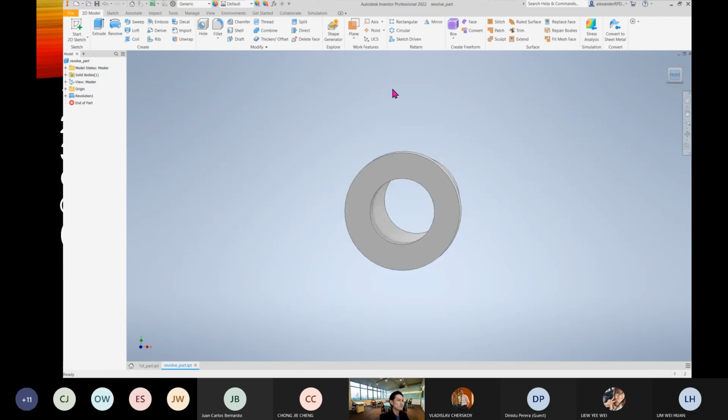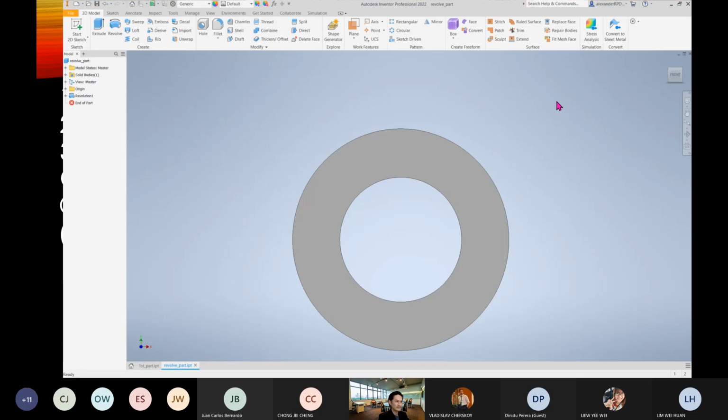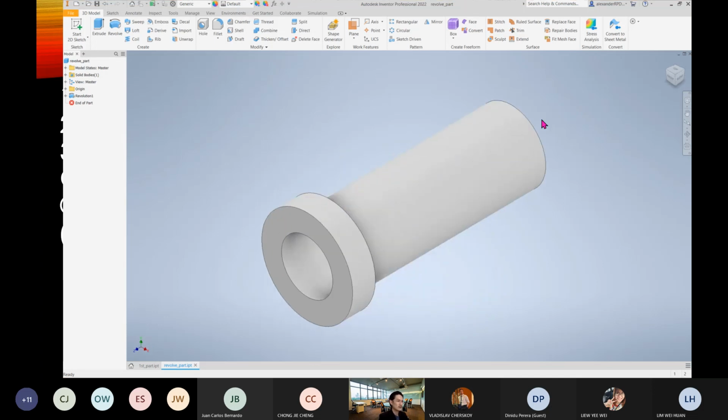Now let's say I would like to create a keyway over here by milling things over here. And then drill a hole later on. So what should I do? Because you cannot start a sketch on a non-flat face. You can see that if you want to start a sketch on the curved or circular face, it is not allowed. It will only detect the flat face.